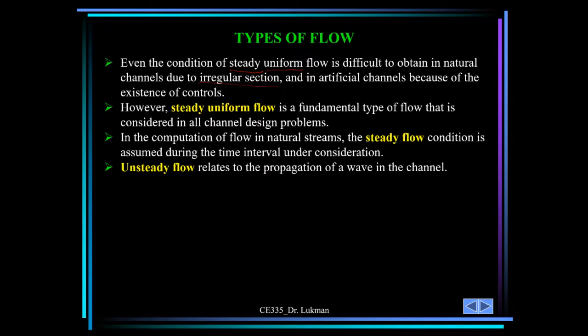However, steady uniform flow is a fundamental type of flow that is considered in all channel design problems. So for design, we consider the flow to be steady and uniform. We mentioned clearly that it's difficult to obtain in natural channels because of the irregular section.